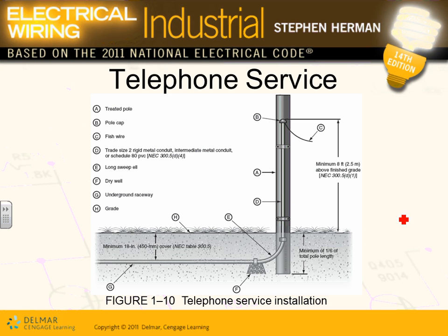Another thing, Karen, that we do on the site also, they show telephone service and electrical service and what's not. Here's an example of a telephone service coming to your building, guys, from the phone coming underground, from the top all the way going underground into treated pole, pole cab, and fish wire. They have the fish wire, so you can fish your wires right through it, all the way through the 18 inches depth of the conduit. They're going to pull your phone wires or coaxial cable.